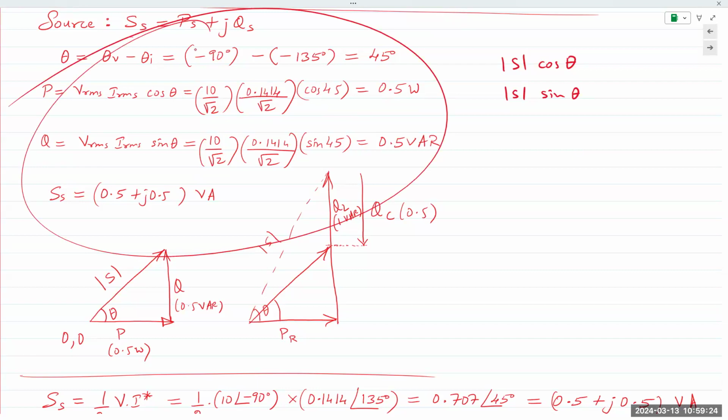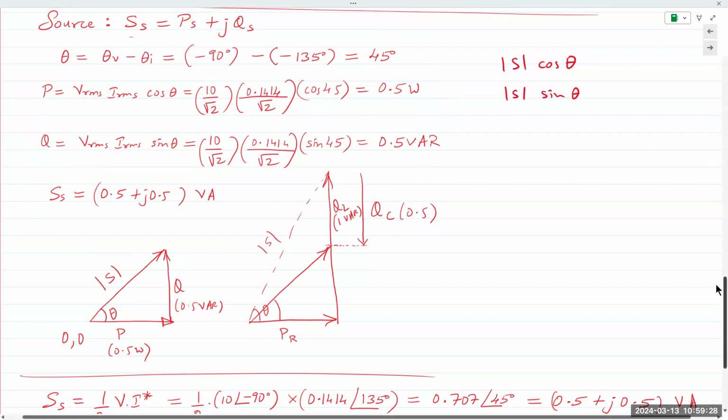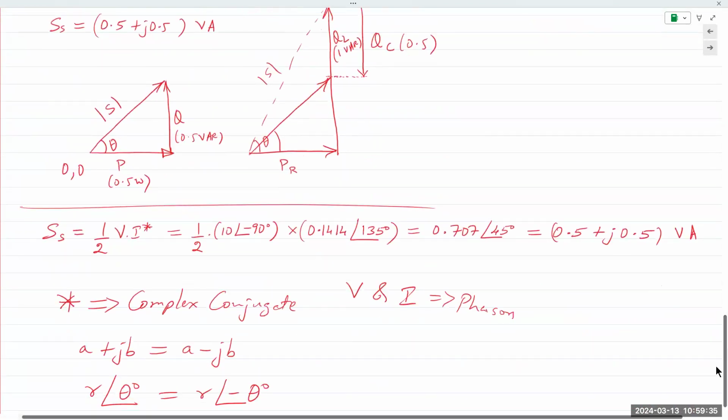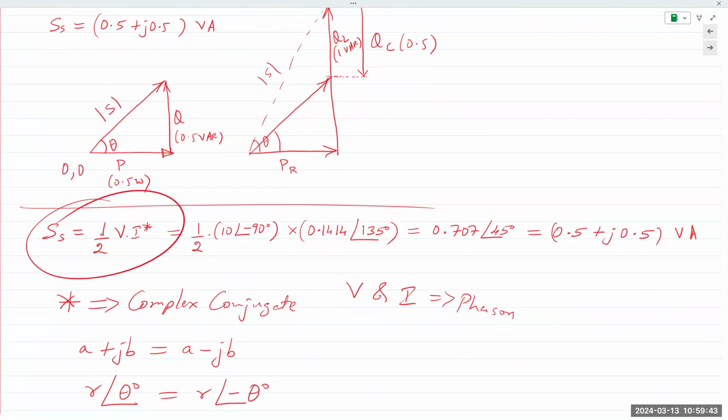There is also another way, a third way to find power, which is listed below, which is even easier. That's a one-step answer, which is to use the product of the voltage and current. Real power P is VI. Remember, I said it at the beginning, VI. For complex power, that equation still holds true, but mathematically, we have to take the angles into account. So it comes out to be half VI asterisk.